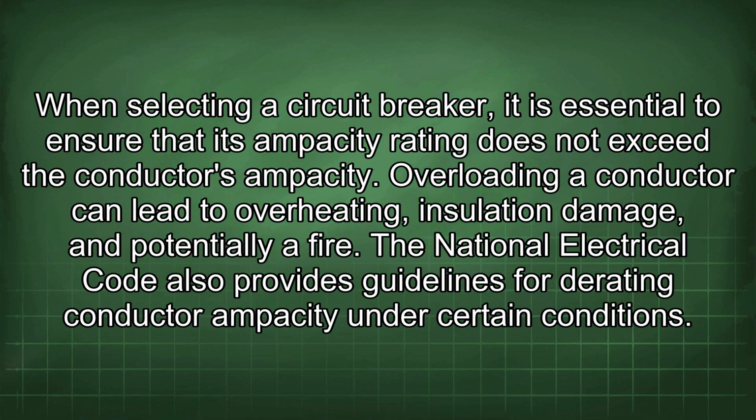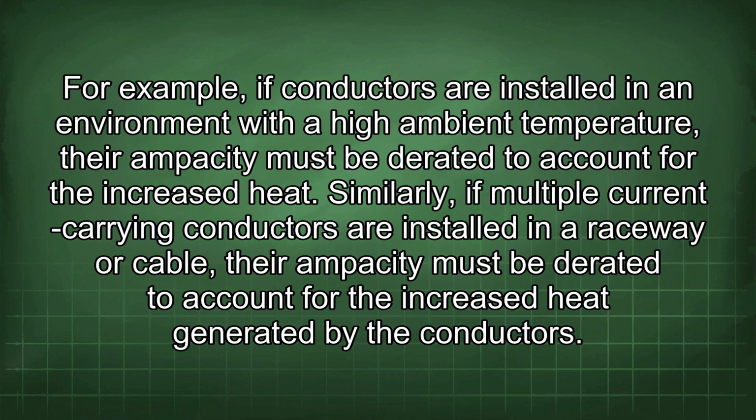When selecting a circuit breaker, it is essential to ensure that its ampacity rating does not exceed the conductor's ampacity. Overloading a conductor can lead to overheating, insulation damage, and potentially a fire. The National Electrical Code also provides guidelines for determining conductor ampacity under certain conditions. For example, if conductors are installed in an environment with a high ambient temperature, their ampacity must be derated to account for the increased heat.